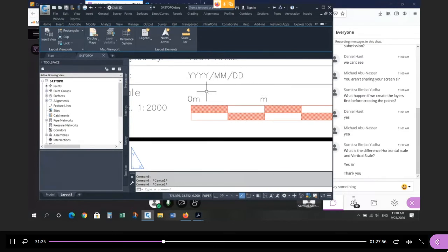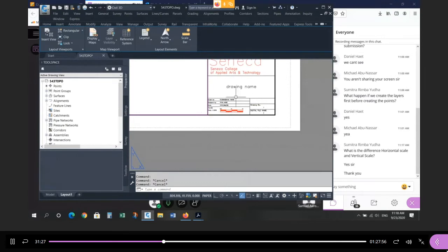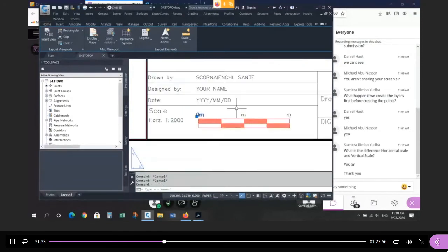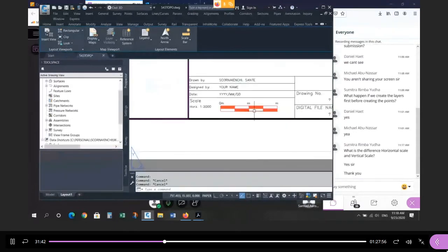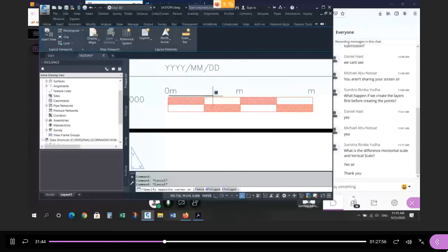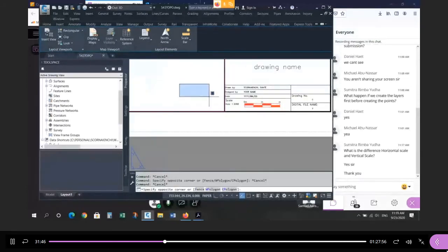Everybody understand? Right? This is in paper space, but the distances in model space have a scale factor, right? Half size. So the distance from here to here in paper space is not the distance you see here in model space. So you need to determine in paper space, what does this distance represent in the viewport? Okay? And I'll give you a hint.